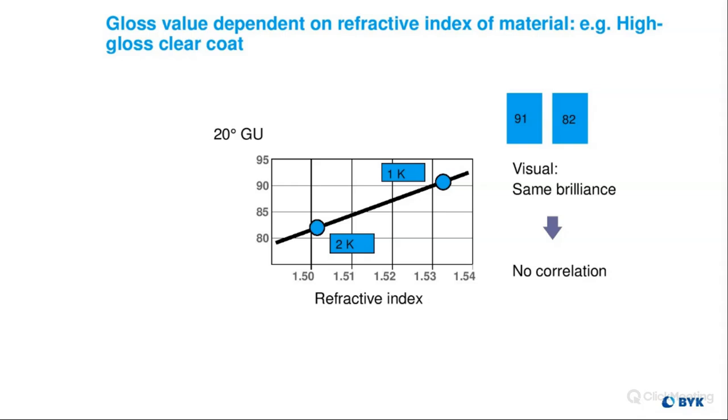So it's not typically recommended to measure very hot samples, because you might get a different value when you measure the hot sample versus when it's cooled off and you measure it again. That's due to the heat affecting electronics, and that's not particular to gloss meters, but goes for really any type of electronic.